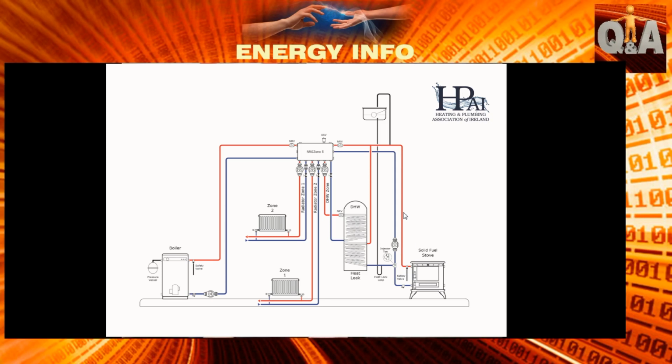Can I say there's a really important thing to talk about with solid fuel? If water ever reaches above 80 degrees on a return pipe or on the flow in the stove, the pressure difference between the temperature rising water and the falling water is perhaps negated, because it's so minimal that in fact the thermosiphon might stop working. And that's why I don't particularly like devices that rely on flushing water, whatever. You need the water to move, and you should be moving it well before it ever gets close to 75 or 80 degrees. There should be good circulation at that point before you hit it. That's very important.